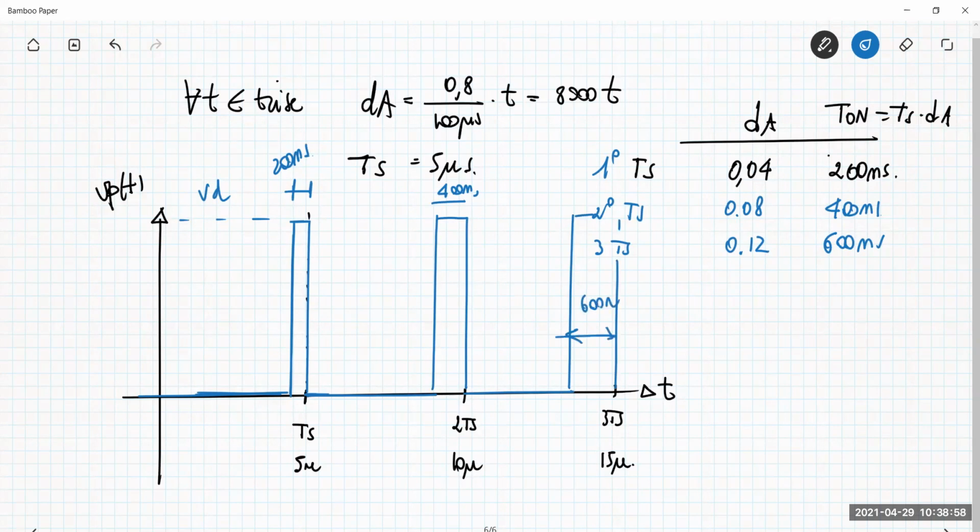If I plot all the 20 TS intervals, from say 0 to 100 microseconds, then the duty cycle at the end would be exactly 0.8, which is exactly the duty cycle I need. Okay, so just focus the attention on the first 3 time intervals, because this is the voltage Vp that I have due to the transistor Ta plus that is switching on and off.